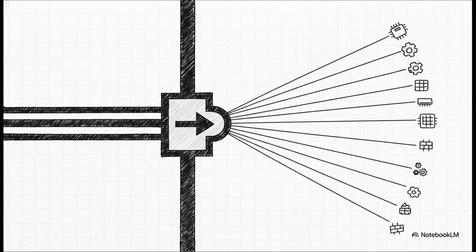We aren't just talking about abstract theory anymore. This is a massive, real-world switchboard. It takes a 4-bit input and decodes it into 16 distinct outputs. This exact kind of logic is used in memory systems right now to identify CPU locations. It selects functional units inside microprocessors, and it directs signals to different physical rows of memory chips. It's essentially the main traffic director for your computer's brain.